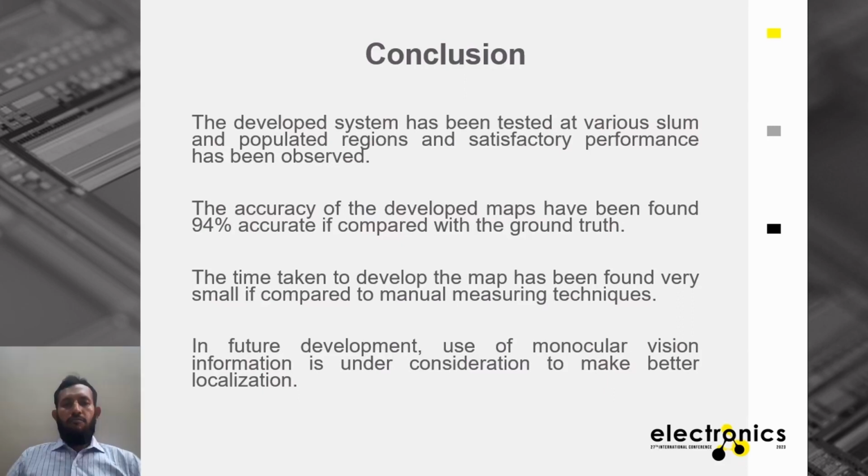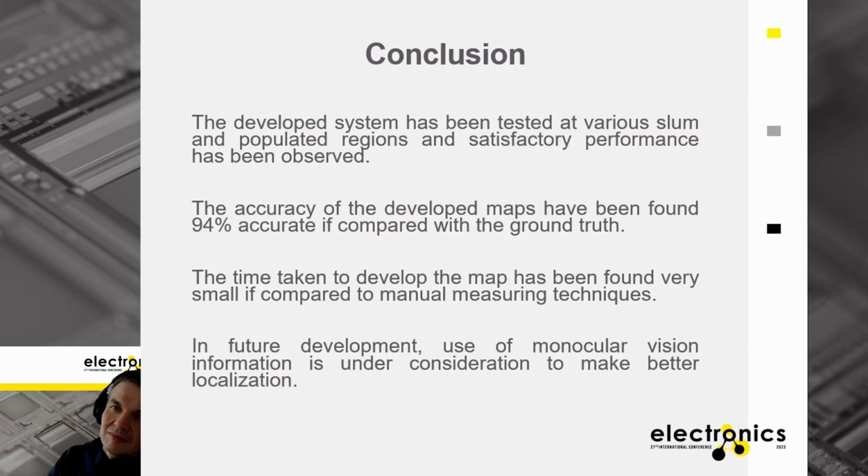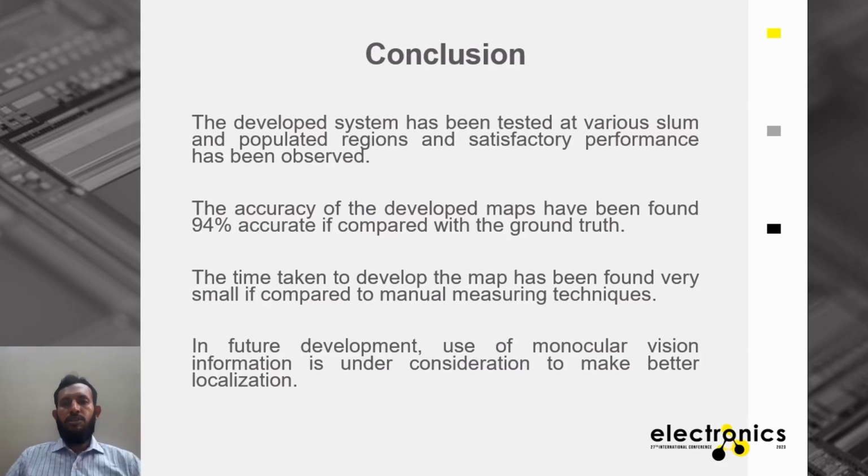Yes, actually, we have analyzed all the sensors which are providing the data, and right now we are finding that the GPS always has some errors. Then we are using the stereo camera, which also gives some errors. So that's why we now have only some limited sensors available, for example, the monocular vision, which has single-direction vision information rather than a huge amount of information. So maybe we can use that split information for these kinds of issues, and then we can find better localization values, especially in the Z-axis.